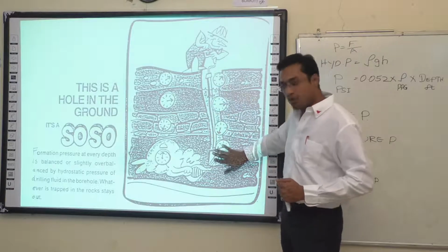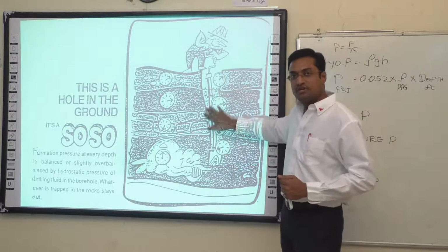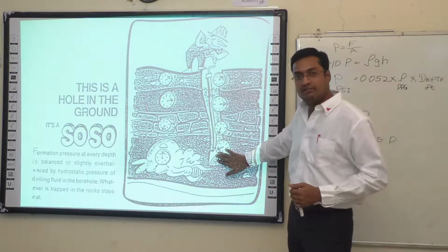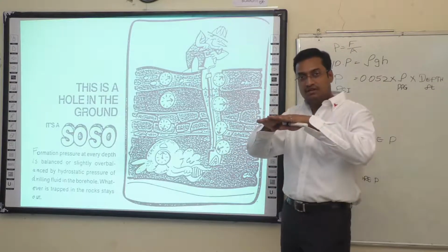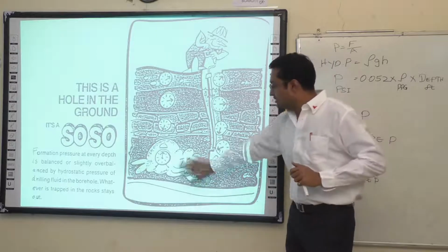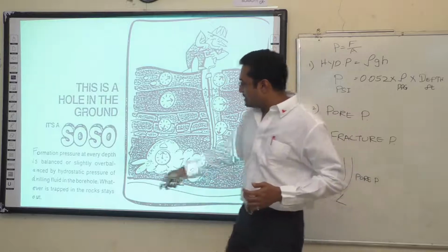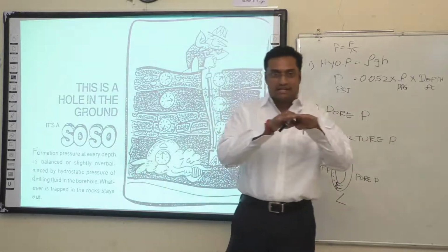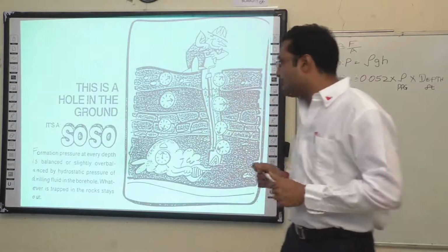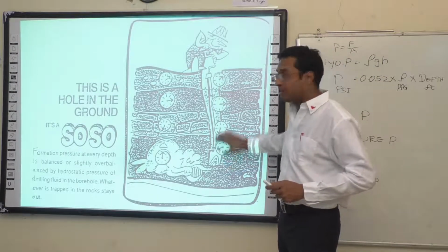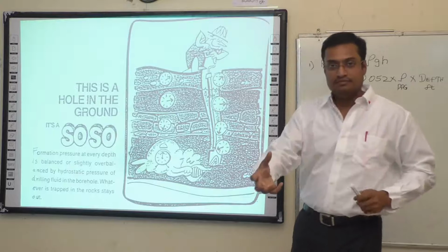So the deeper you go, the formation pressure is more. So we have to maintain the hydrostatic pressure balanced or overbalanced to keep it at rest. So the formation pressure at every depth is balanced or slightly overbalanced by the hydrostatic pressure caused by the drilling fluids.